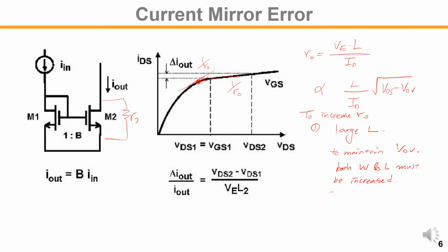current density over the transistor. Why do we want to maintain the V overdrive voltage? Because that also results in the sensitivity to current variation. We want to have a large overdrive. If we have enough headroom, then the ID current variation to VTH variation would be small. So if you put too small a V overdrive, then the